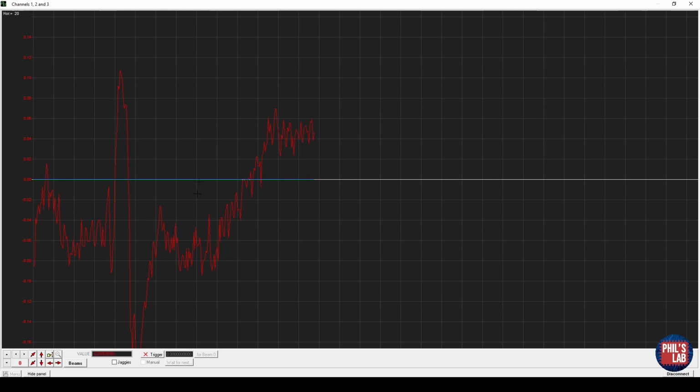So you can see this random walk, it goes below and above this 0 line, and it hopefully is constrained between plus and minus 10 centimeters, even though you can see there's a tendency for this measurement to drift upwards, and you can see it's starting to drift down a bit as well. So for the way we are calculating the altitude, with our constant coefficients, we're not doing temperature or density of the air compensation, we're getting about plus minus 10 centimeters.